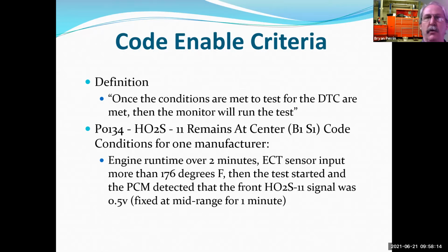In other words, I have a code that might be a little more complicated, maybe a system code that involves 3 or 4 different expensive pieces that are hard to test. So I might do some research and find, is this code common for this car? What normally fixes this code? So that way I can spend my diagnostic time testing the component that fails the most often, right?